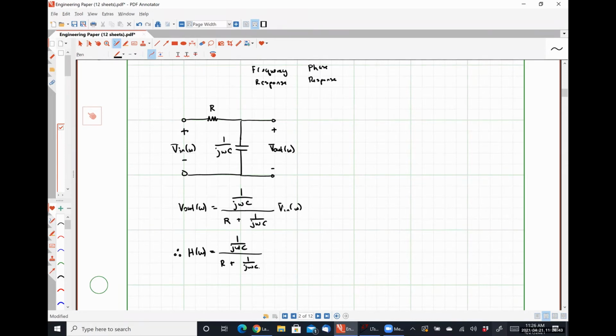So our transfer function is always just going to be the ratio of the impedances portion of our voltage division equation. Another way to think about this is we could just figure out what the output signal is if V in has a phasor value of 1 angle 0 degrees. If we treat V in as 1 angle 0 for all frequencies, then V out is exactly the same as the transfer function. So again, it's just simple voltage division.